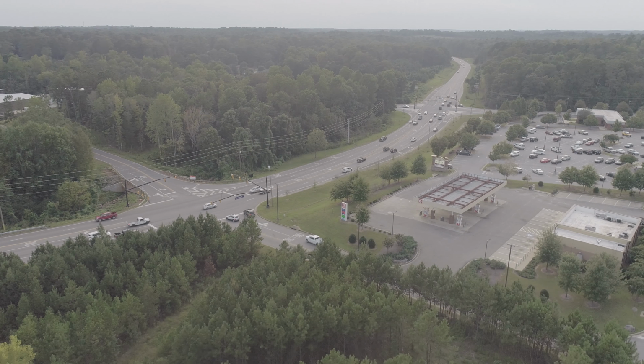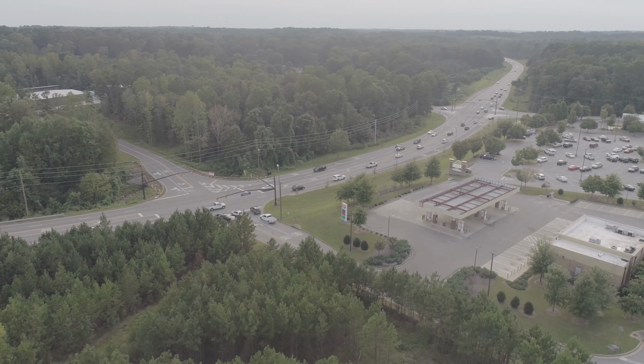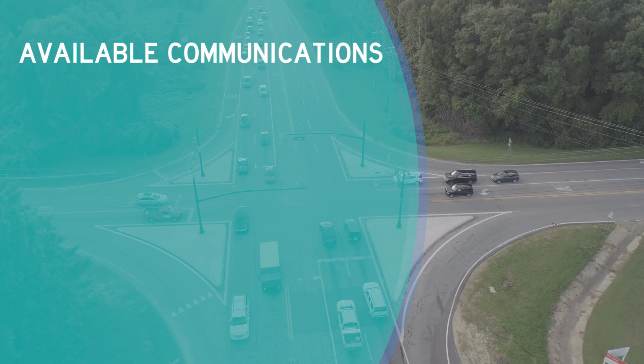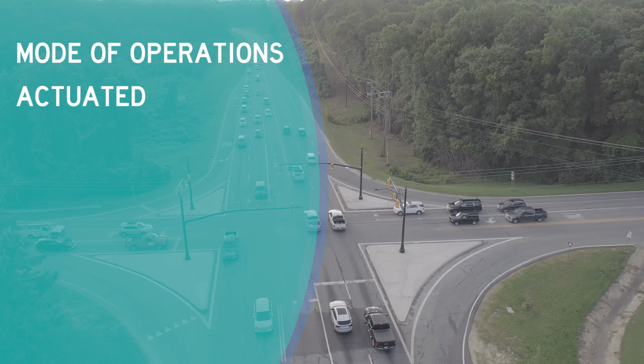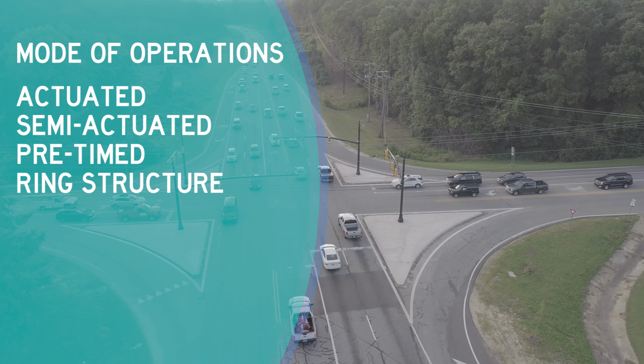Next, we will need to determine if the location works in coordination, and if so, determine the type of coordination system used. We will also need to know the available communications, such as TP, fiber, RF, or other types. The mode of operation, such as actuated, semi-actuated, pre-timed, and the ring structure are also important inputs.